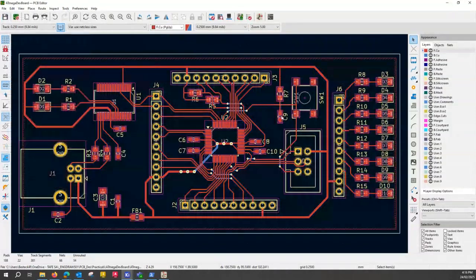And I need to stitch top and bottom layers together. So I'll select the wire tool, and I'll just place one, and with stitching, I usually stitch boards along the edges and then do some critical points and important points on the board. So I'll start with that corner here somewhere, place it down.